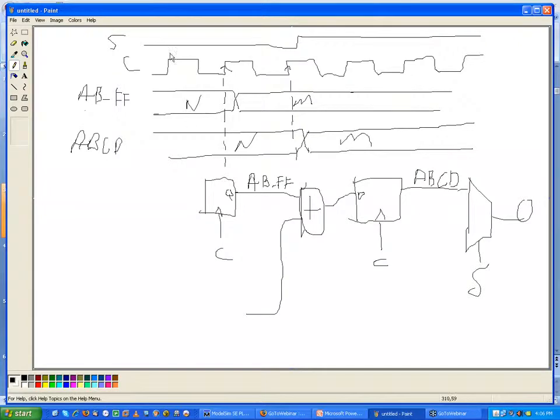Okay, so based upon whatever your cycle time is, let's say this was 10 nanoseconds from rising edge to rising edge, and this clock to Q was 1 nanosecond. The wire plus all the logic delays was, say, another 6 nanoseconds, and you had a setup of 2 nanoseconds.